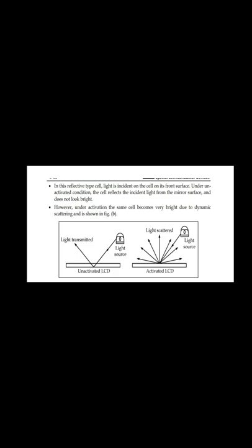When no electric potential is applied between the two conductive coatings, there is no movement in the liquid crystal molecules. That means the liquid crystal keeps its default definite orientation, so its orientation will not change. As a result, the display is black in color.